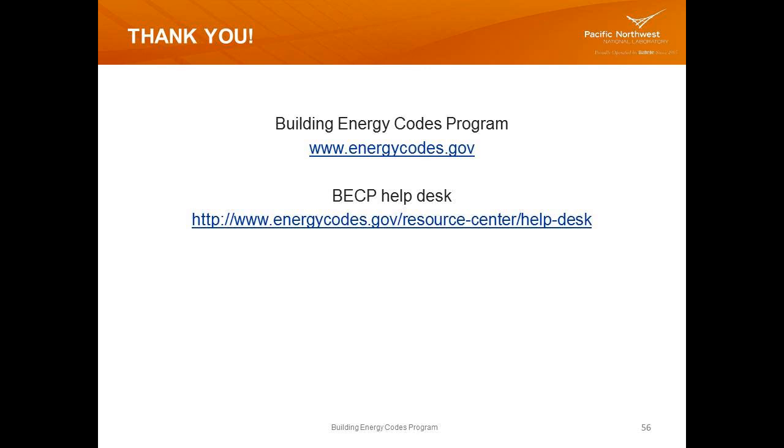Usually it's under your user account, AppData, Roaming, COMcheck. That's where you'll find fixturelibrary.xml. If you want to make a copy of that and send it to a coworker to share, you can do it that way. Or if you want to preserve it because you're having to move to a new machine and you want to have access to it on the new machine, copy that to disk or a share drive somewhere.